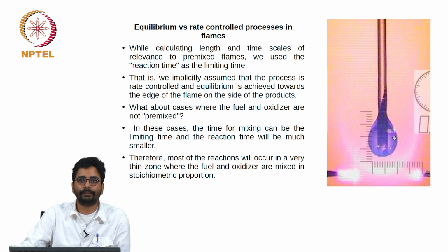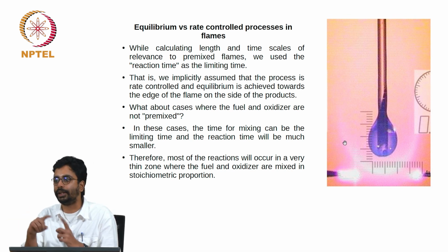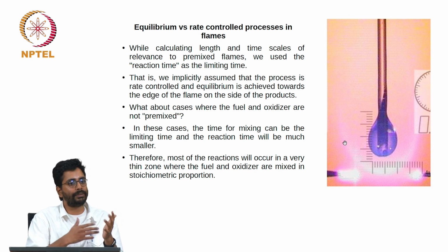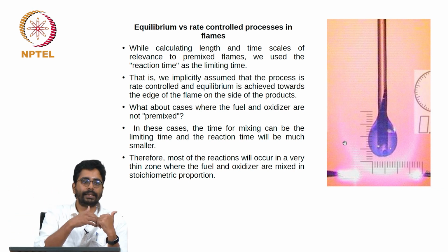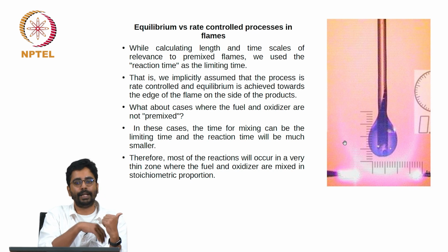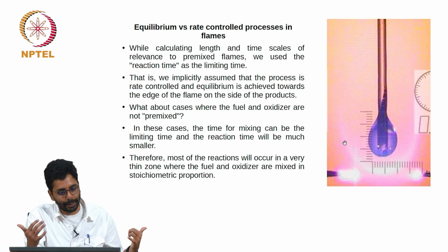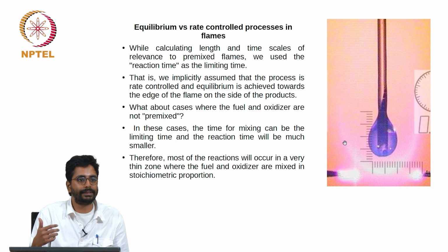This flame is formed by the reaction between ethanol vapors that come off from the surface of the droplet, mix with the air from the surrounding and react and form a flame. So this is a non-premixed situation, not a premixed situation. Ethanol vapors come from inside of the flame, oxidizer diffuses from outside of the flame, both diffuse towards the flame, mix and react. In fact, they move towards each other, mix and react, and the point of maximum reaction is the flame.